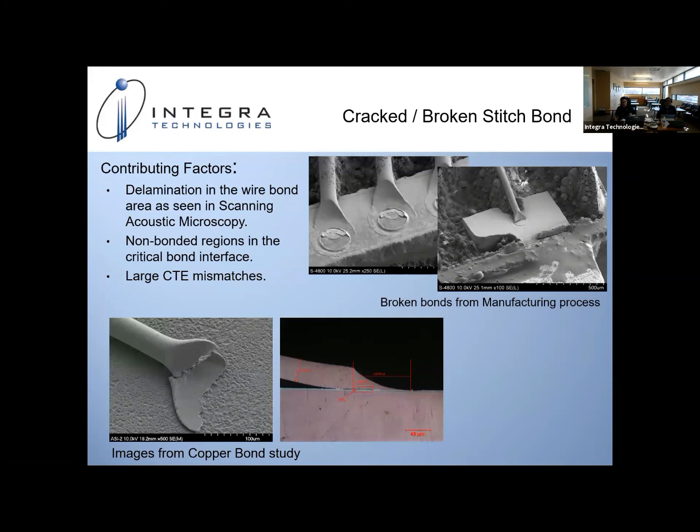This shows some of the other problems. There's a crack or broken stitch bond, and there is an actual case or cases in which the delamination on top of the wire was attributed to the actual failure of a stitch bond that resulted in a field failure.